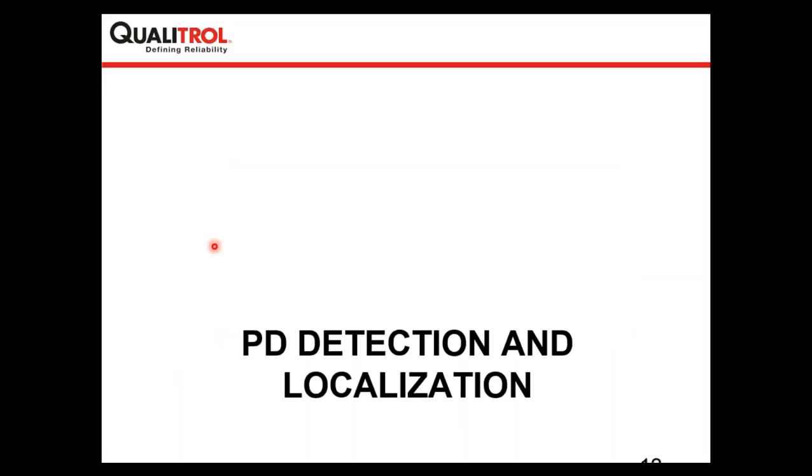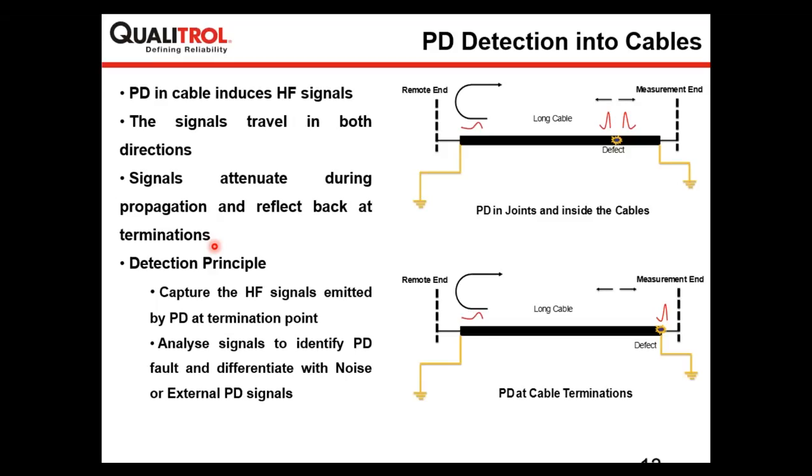So, a little bit of theory about the detection and the location of partial discharge. Now we are going to start. Suppose there is a defect in the power cable. Whenever you have a defect, there will be electrical pulse currents. Two pulses of equal magnitude will be generated from the defect side. These high frequency current pulses will be traveling towards the different ends.